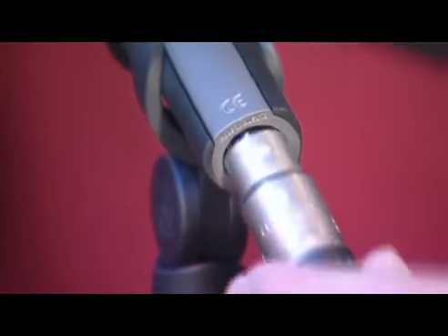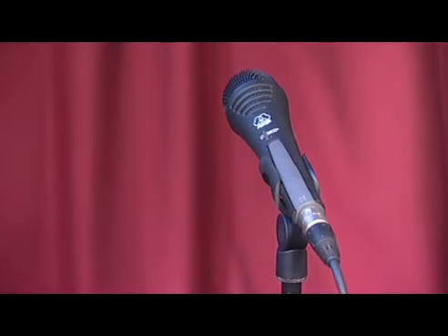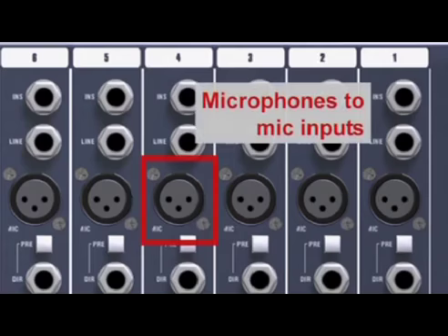Microphones use balanced XLR cables. Don't use line inputs for microphones. The plugs won't fit, and even if you use an XLR to jack adapter, the levels won't match.